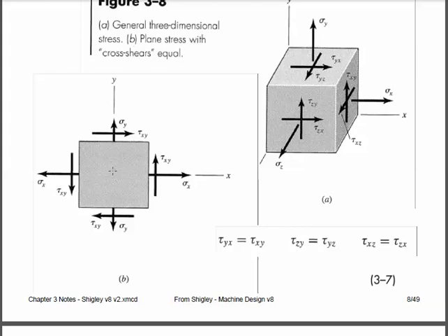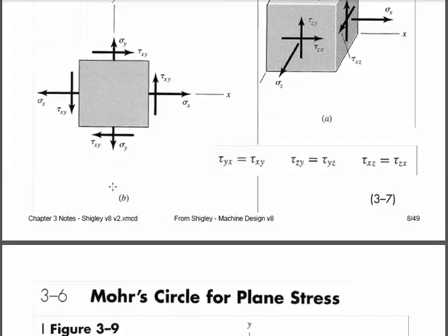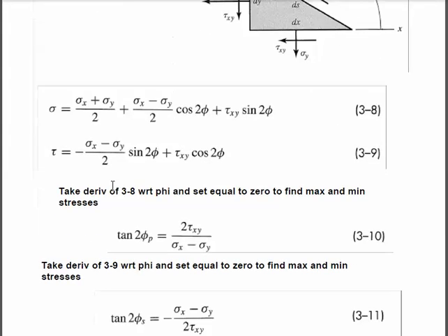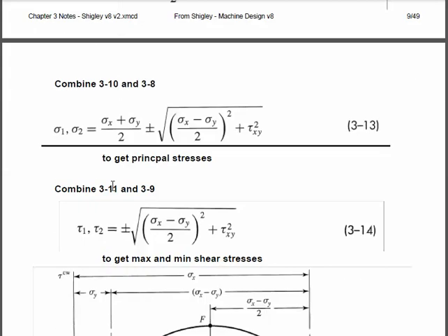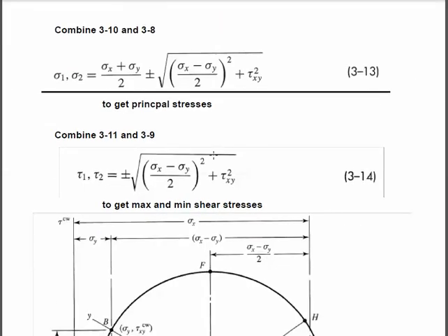Okay, from this we learned how to do Mohr's circle. From this we understand that there are really 3 Mohr's circles when we get to the principal stresses. Mohr's circle is derived here. I wouldn't grab any of these equations. I wouldn't expect to need them. But finally, the final equation for getting the principal stresses that we later on called sigma A and sigma B out of Mohr's circle, that came from plane stress, because we only get 2 of them from the plane stress circle. And it includes a location of the center of the circle, the average of the x and y stresses, and the size of the radius of the circle that involves the x and y stresses and the tau stresses.